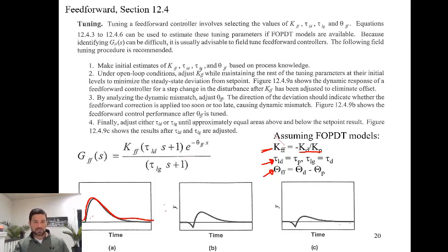So as soon as the disturbance occurs, again, this right here is the control variable, so we're not measuring the disturbance here. But the feed-forward controller, these lead-lag elements, are designed such that the feed-forward controller can cause a corrective action to occur. So as we measure the disturbance, we can start having the disturbance change the manipulated variable, which is going to cause the process to change. Right? We don't want the process to change too much by our feed-forward controller in the negative direction, because eventually what happens is we change our manipulated variable, it affects the process, and then the disturbance combined with our manipulated variable is going to get our process back down to steady state.